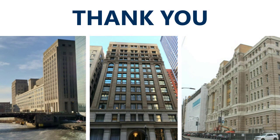Yeah, in that regard, even if you go through a full document set and have standard costs instead of itemized costs, it's always good to have unit costs for things that you think might come up and might be covered under that, tuck pointing, sealant work, things like that, in order to have something as a basis. So when you get into an unknown, you can say, well, your unit cost for this was X, and your unit cost for that was Y. This repair has both of those, so let's get a price that falls within those two unit items.